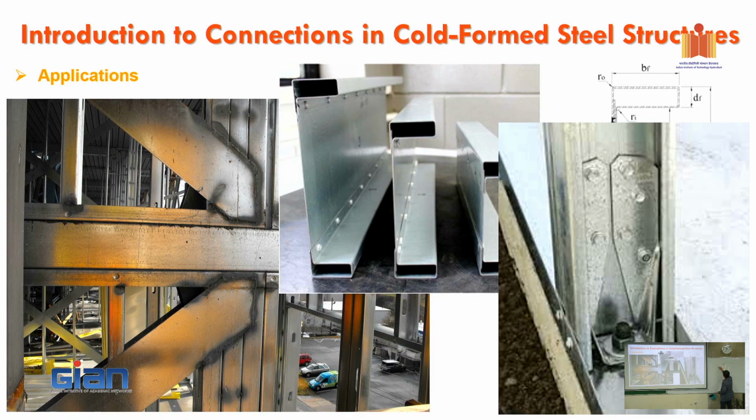It's going to be like that. Right, so instead of you got a shear in here, you're going to have a big load in here as well, which just lifts that one up. Right, so this is very important. If you don't hold that one, then that one just twists, rotates, that one is going to go up. So that is one of the very important bits in our structural component, not just the shear wall itself, but those you need to pay a lot of attention to.